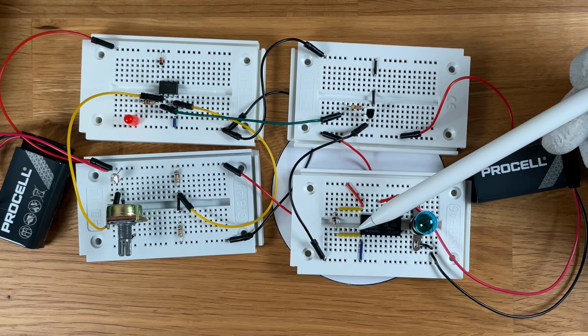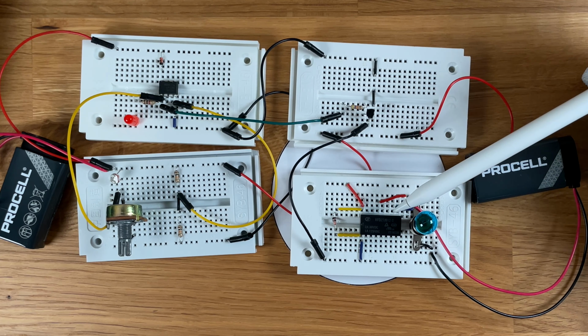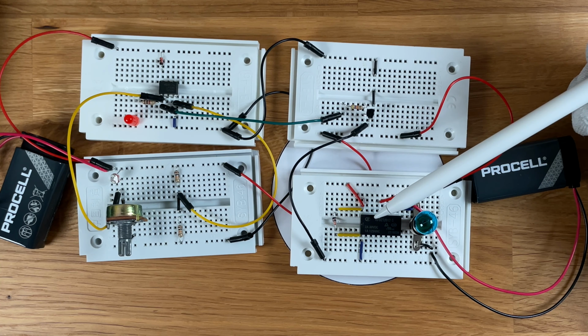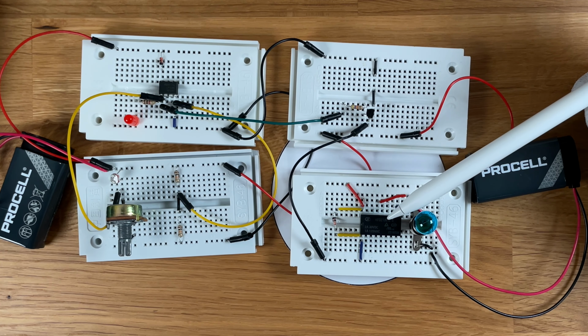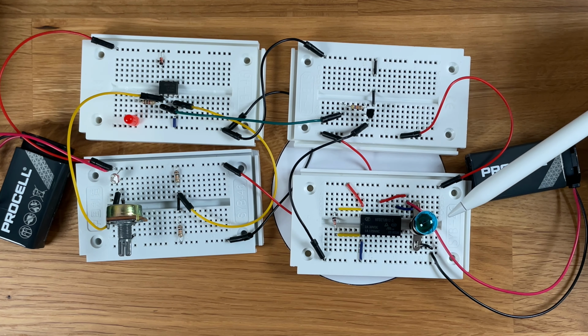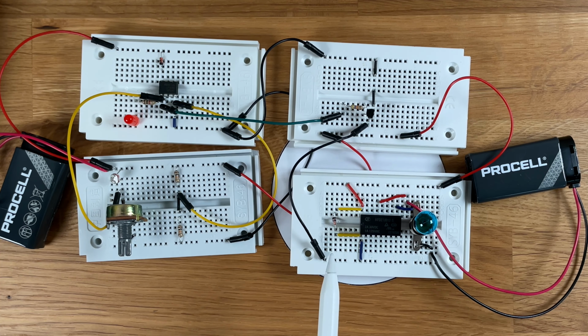The circuit on the left is triggered by our setup here. The circuit on the right contains a different energy source. It could also be another battery. It could be the wall socket, but for using the wall socket we would need another relay, which is suited to 230 volts of power in the German net. This one is only suited for 30 volts, but basically we could do it in this manner, and this then lights up the LED. So we are switching another circuit by using our setup here.